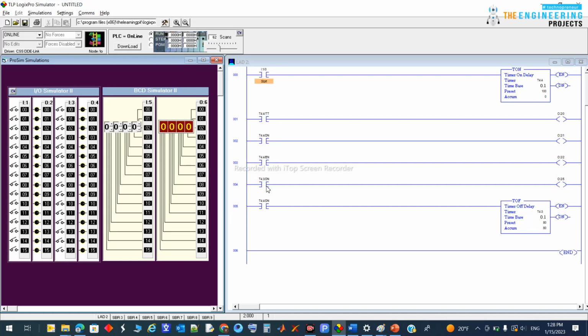And also I'm going to continue this session with another kind of timer. So we have the retentive timers, in which we can accumulate the timing for a long period. For example, imagine, my friends, you have to know for how long a specific piece of equipment, like one pump or one motor, is working, or machine number 15, like I want to make maintenance after 1 week, or after 1 month, or after 1 year.